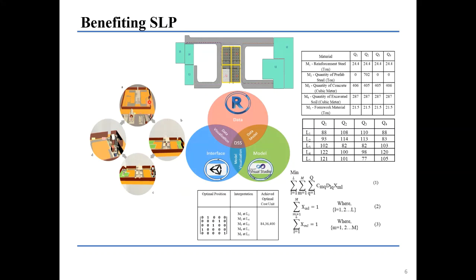Once your application starts, you get the option to select a project. Following it, you will get to know what temporary facilities are going to be employed on that construction project. Once you initialize the application, every required temporary facility is set back to 0,0,0 coordinate. Following it, once you hit run, you will get to know the optimal positioning of those temporary facilities. And this is the point where you receive at least a single optimal solution in the pool of solutions which is generated by the genetic algorithm.